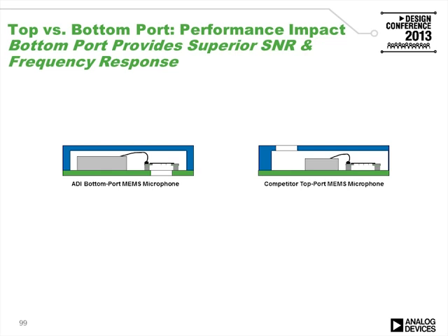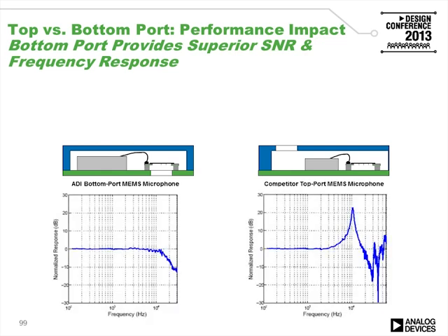If we look at the frequency responses of these two microphones and compare them to each other, you can see that the bottom port microphone has a pretty flat frequency response, which is what you might expect or might want. But the top port MEMS microphone has a sharp peak in its frequency response right around 10 kilohertz, which is well within the audio band.